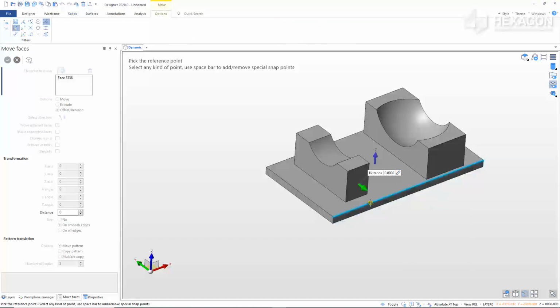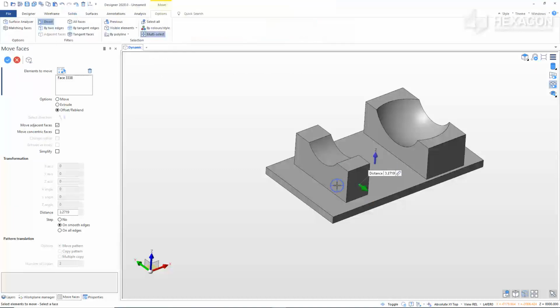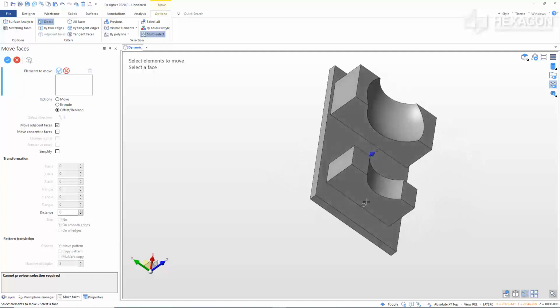Now select anywhere on the front face or edge of the fixture plate. Move the cursor to see the modifier. Fill in the modifier with 50 for the measurement and hit Enter. Right-click to confirm. This will set the edge of the nest block 50 mm from the edge of the fixture plate. Now we will repeat the process with the opposite face of the nest block.